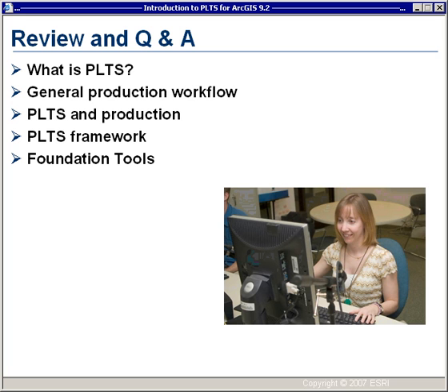Last question. What are the additional tools in PLTS that can aid in feature collection and updates? So Sandy referred to this in her demo, and if we had to summarize which of the editing tools would be at the forefront, I would say it would be the PLTS Selection and Target tab, which allows you to do on-the-fly validation of features, not just passive after the fact, so that we reduce the errors that are entered into the database, kind of the stitch in time saves nine principle.